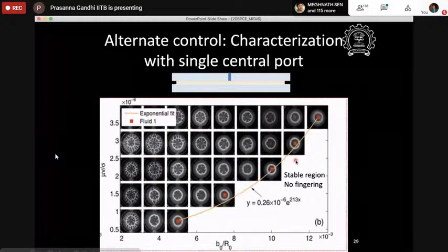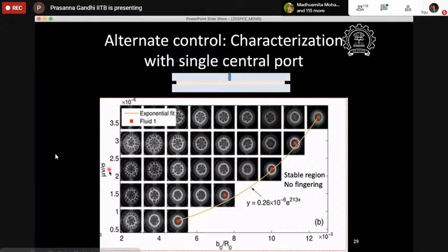So now we again characterize with a single chart what geometry will evolve, okay, in terms of some non-dimensional numbers. This is the capillary number here, and then there is the radius of this circle versus the gap. Okay, this b0 is the gap between the two plates, and R0 is the initial radius to which you expand or squeeze the plate.